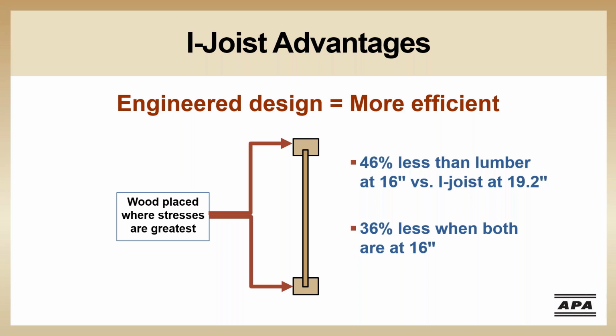9.5 inch, 11 7/8 inch, 14 and 16 inches. Now, while these are the common depths, some manufacturers may also produce other depths. All APA I-joists meet the PRI 400 performance standard at a minimum. You'll see many I-joist manufacturers are going to make products that exceed the PRI 400 minimums, and they're going to have proprietary APA product reports or ICC ES/ESR reports. So when specifying I-joists, it's common to check with the manufacturers for specific engineering properties, and it's also important to check on product availability.